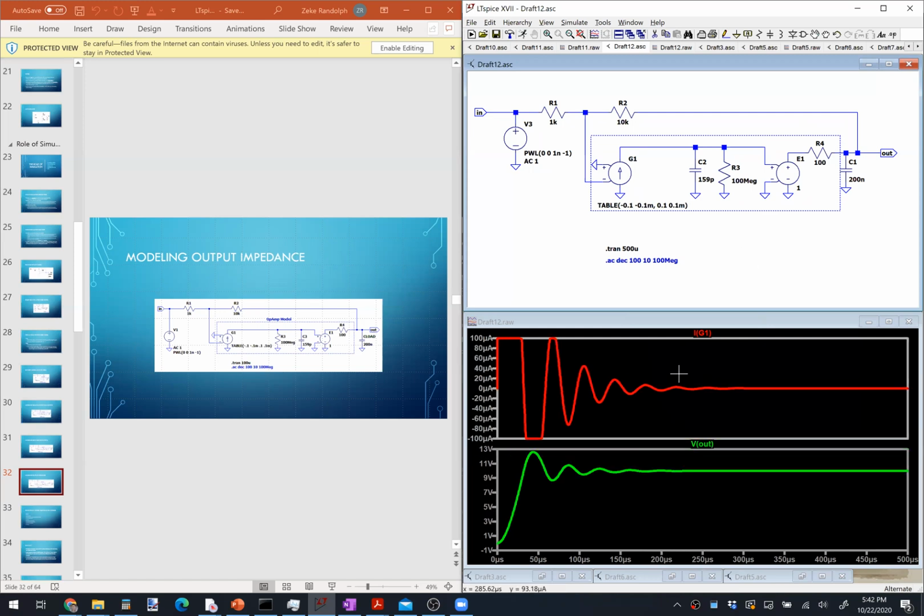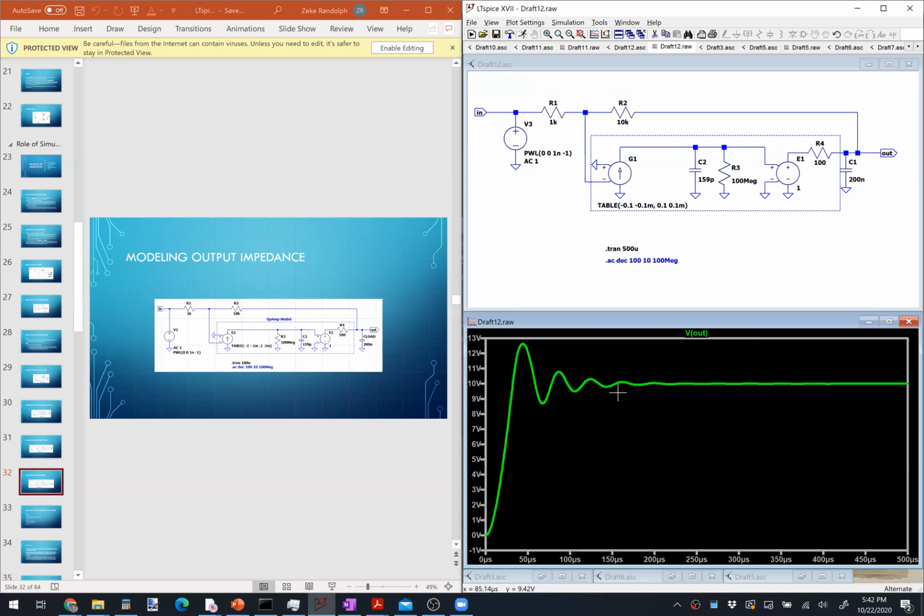There we go. Let me just plot the waveform of the current coming out of that current source. Okay, this actually looks similar to what you saw with the op-amp model for the LT1006. You saw a certain amount of overshoot and ringing until eventually it settled. There are some differences, but without getting too sophisticated into a model, this more or less shows what we were observing. So the lesson you would take away from this train of thought is that by developing progressively more sophisticated models of the op amp, you could eventually find what parameter of the op amp was responsible for causing the undesired behavior. In this case, it was the output impedance, in combination with the bandwidth and so forth.